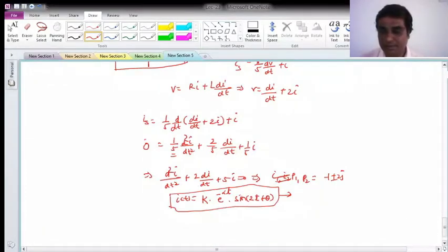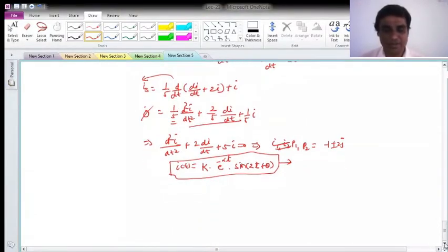Okay. And also to be noted, while we are seeing this, if there would have been some initial energy or initial condition, either initial current through the inductor or initial voltage across it, you can shift it onto the right hand side and you can make everything null, because the characteristic equation is not at all depending on the initial condition, it is independent of initial condition.